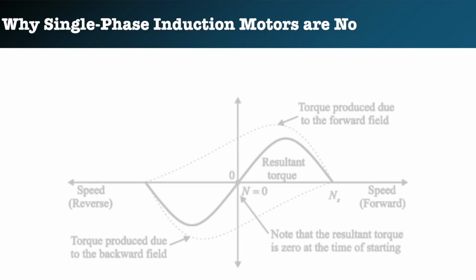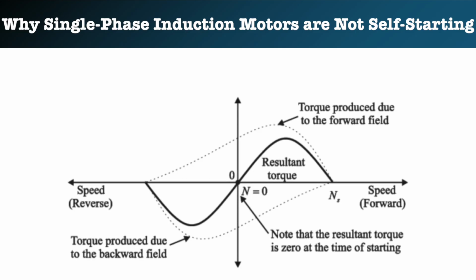As we have been discussing, single phase induction motors are not self-starting. So, what is the reason why single phase induction motors are not self-starting? Let us see in detail. The single phase supply creates a pulsating magnetic field which results in no net starting torque.